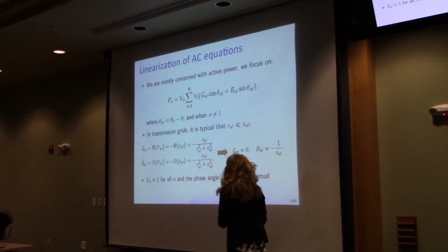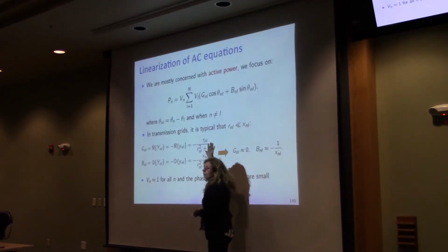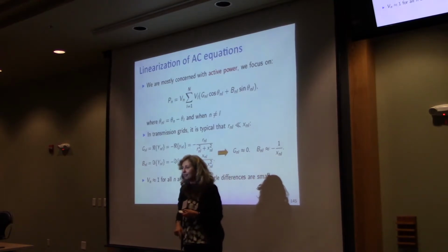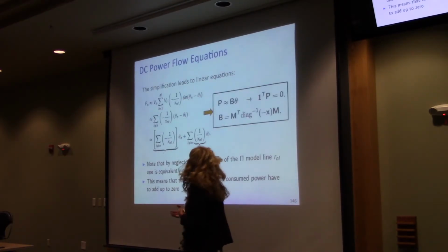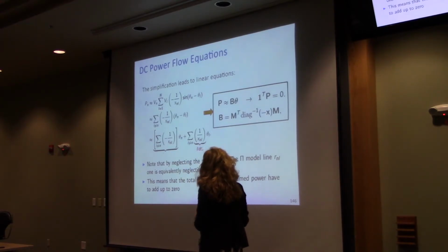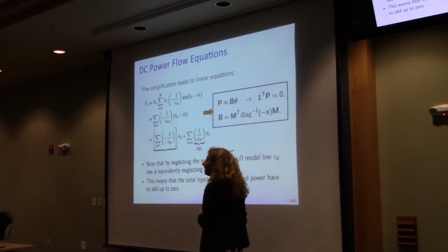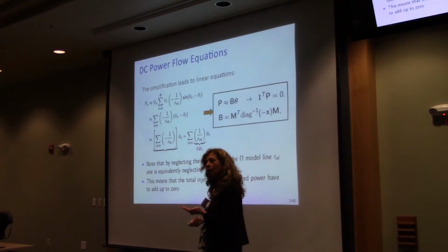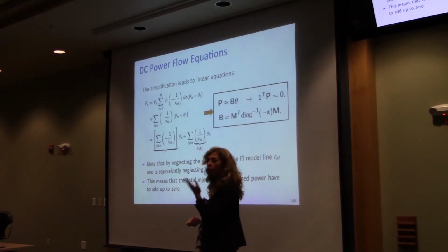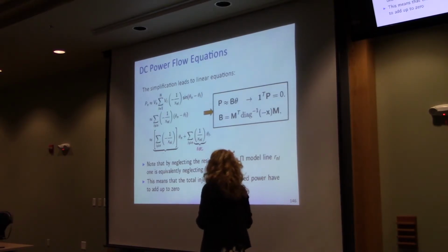As soon as you say that this is small, right, ignore that, you are actually neglecting the losses that you have with it. Okay? So if you have measurements of power and you want to compute the phase angle, you cannot quite do it. You have to assume that you will only calculate relative phase angle. So you fix one of these angles and solve for the rest.